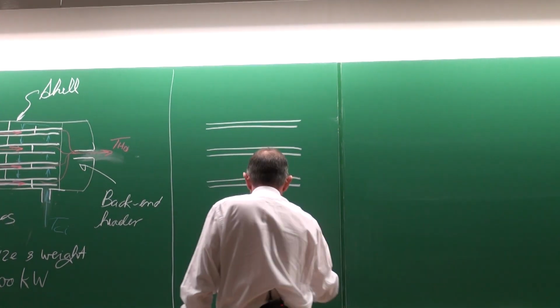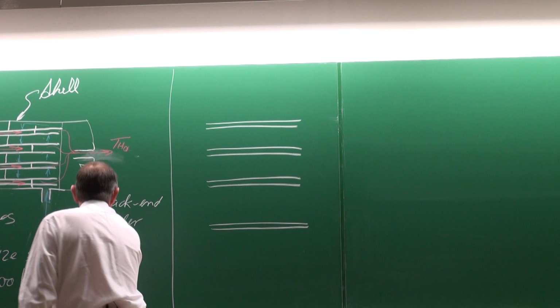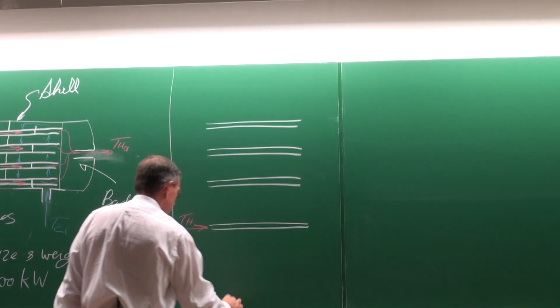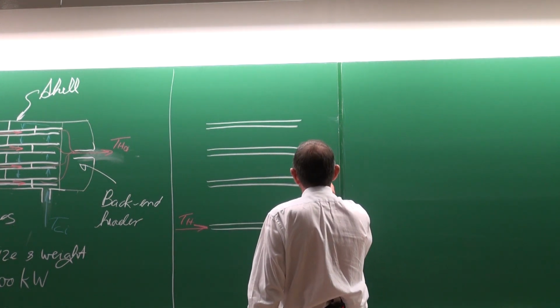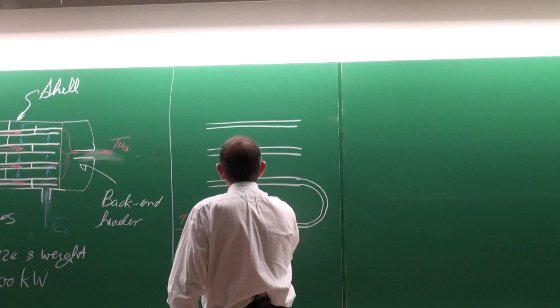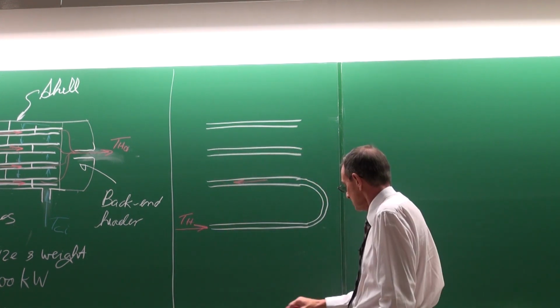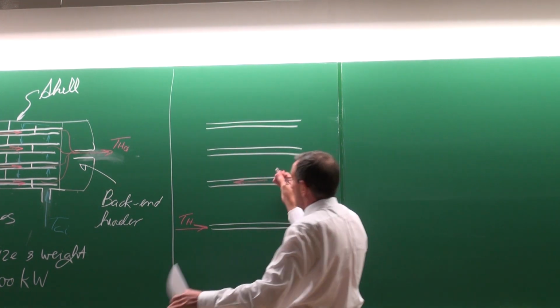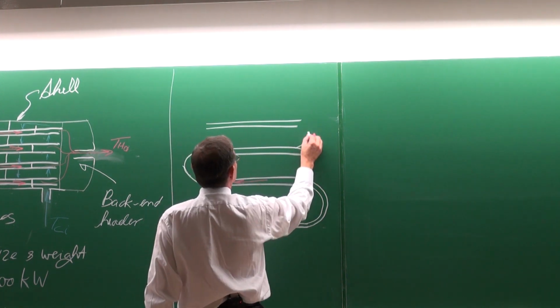you can start doing very interesting things by, if that was now the hot fluid going in there, then you can connect those two tubes like that, which then means that that flow direction switches into this direction. And you can do it only with 2 tubes, or you can even do all 4 of them, typically like that.